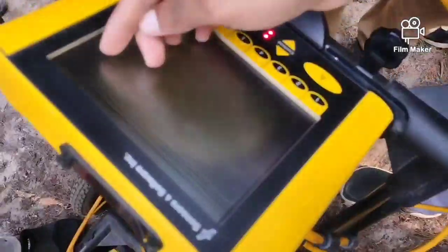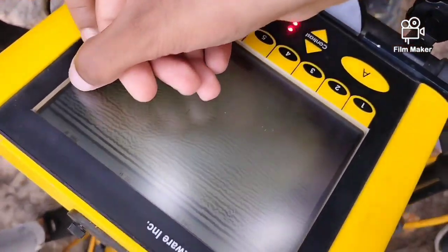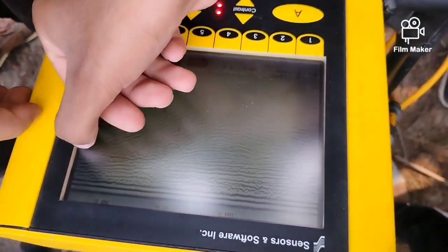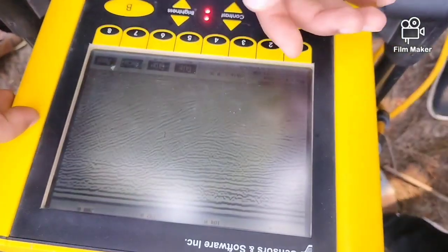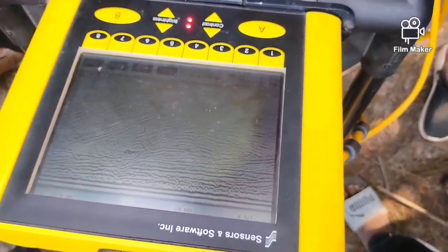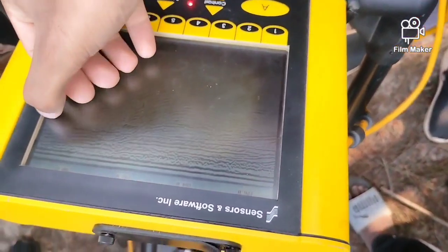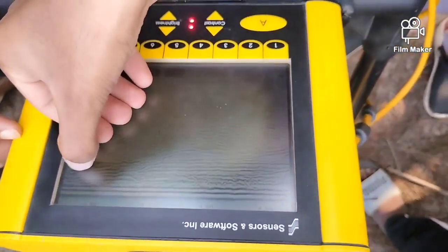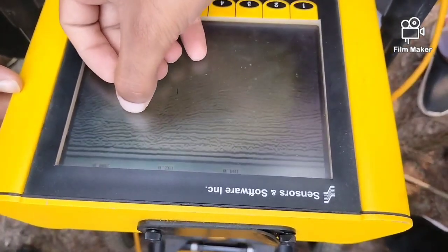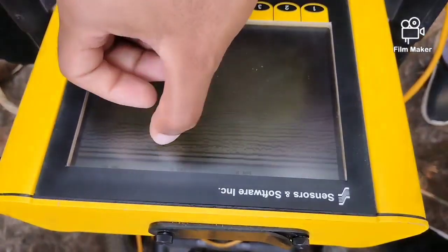But then again, continuing, right? This particular lamination, it's continuing across. Okay, so this is the water table. Water table is because it's air then water, so there's a huge dielectric property contrast. So that's why you get the water table in such a way. But these laminations are continuing all across the water table because this is not a layer, it's just the water table. So all the laminations that you would see are continuing across that particular line.